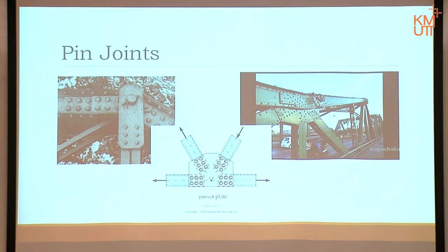The lines of all the member forces meet at one point. If you take moment about that point, you will always get 0 equals 0, meaning it can rotate freely. It won't rotate because it will be connected with something else that stops it from rotating. But by concept, the joint in itself can rotate, and cannot stop rotation.